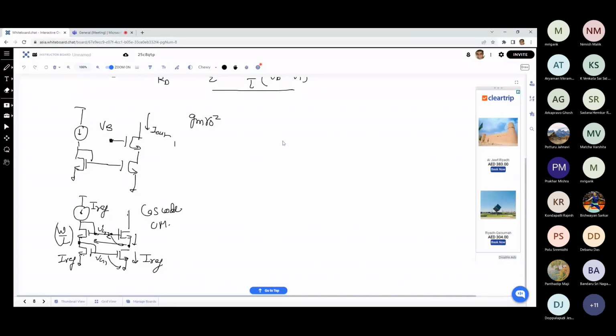But if you talk about the swing, another issue that we have in the current mirror is the signal swing. If I want to find the maximum signal swing at the output, what is the equation for this case, and what will it be determined by? So this is again your IREF, and you're talking about the Vout over here. Vout max is no problem, because if you go higher, it will only be constrained by the upper circuit. So what we are concerned with is the Vout min. What is the Vout min?